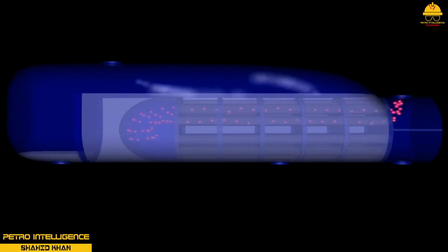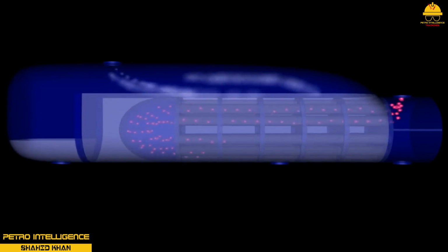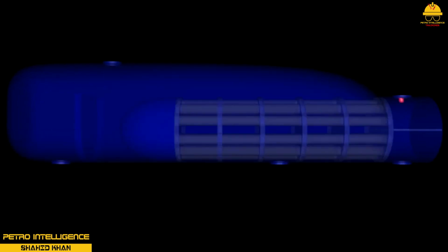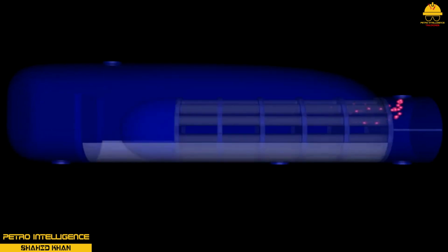A large vapor cavity above the heated process medium allows vapors to concentrate. Liquid that does not vaporize flows over a weir and into the liquid outlet. Hot vapors are sent back to the distillation column through the reboiler's vapor outlet ports. This process controls the level in the bottom of the distillation column, maintains product purity, strips smaller hydrocarbons from larger ones, and helps maintain the critical energy balance on the column.